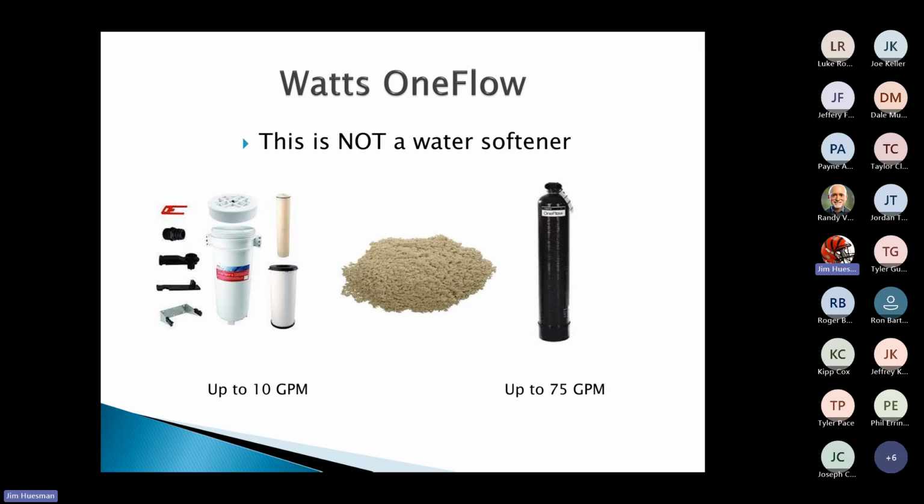To change the media out on a system like this, by shutting the water off, loosening unions, and bringing it out, you should probably allow roughly 30 minutes the first time, and you'll get a little quicker afterwards. That will be the same with our light commercial residential. We want to change that media out at least once every 3 years. If we don't, it's no good. So get that replaced either with our cartridge or by adding into the tank.